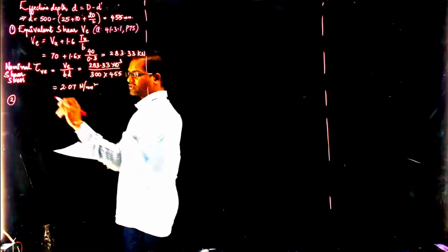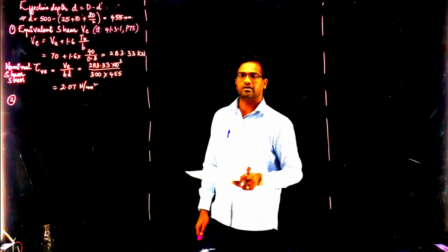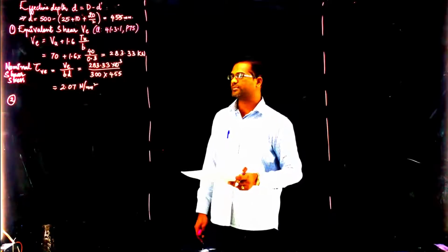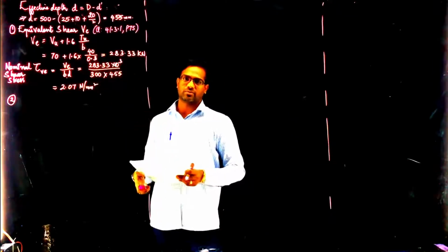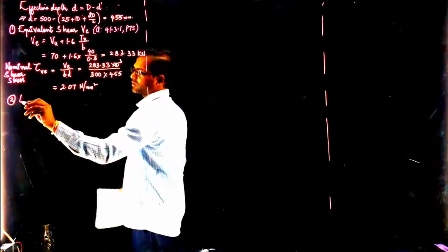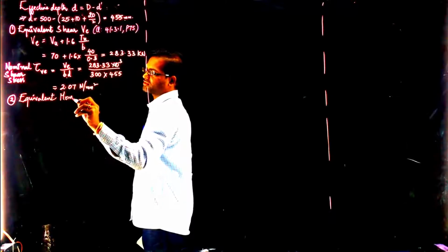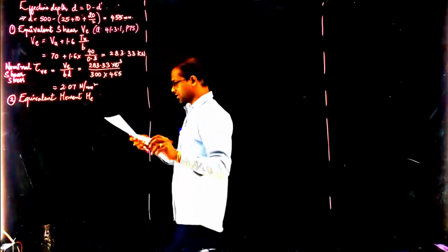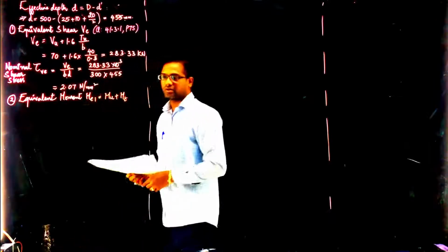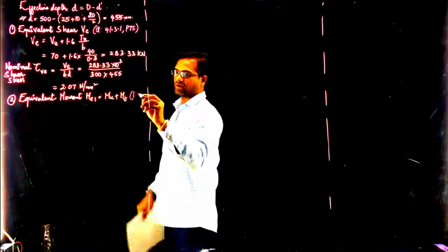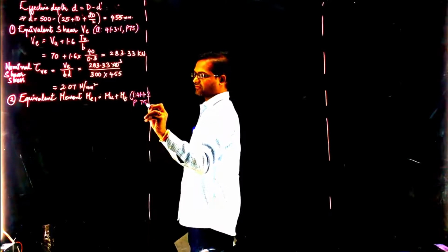Now, this is helpful in calculation of shear reinforcement, that is stirrup. And if you want to calculate the longitudinal reinforcement, then you need to calculate the equivalent moment, because you have torsional moment along with the flexure moment. So the equivalent moment Me1 is given as Mu plus Mt. This is again stipulated in clause number 41.4.2 in the same page number 75.